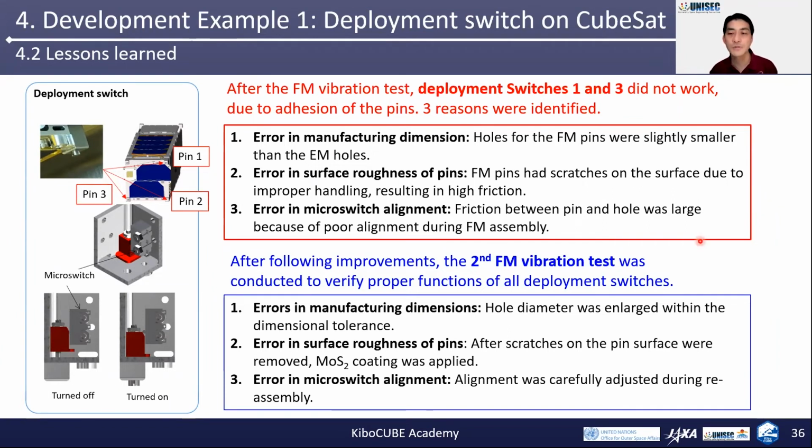Third, the microswitch was misaligned. We found that the friction between the pin and hole was larger in the flight model than in the engineering model because of poor alignment adjustment during the flight model assembly. Then after the following 3 improvements, the second flight model vibration test was conducted, and we could verify the proper functions of all deployment detection switches.